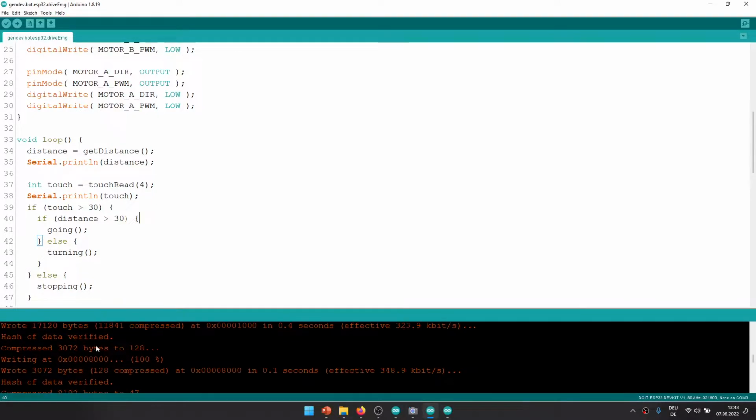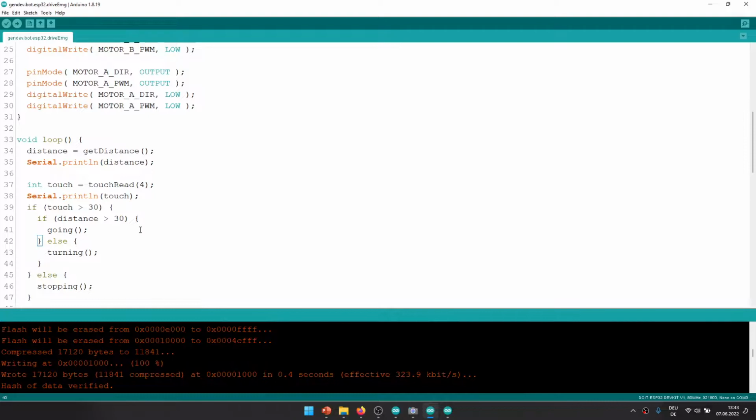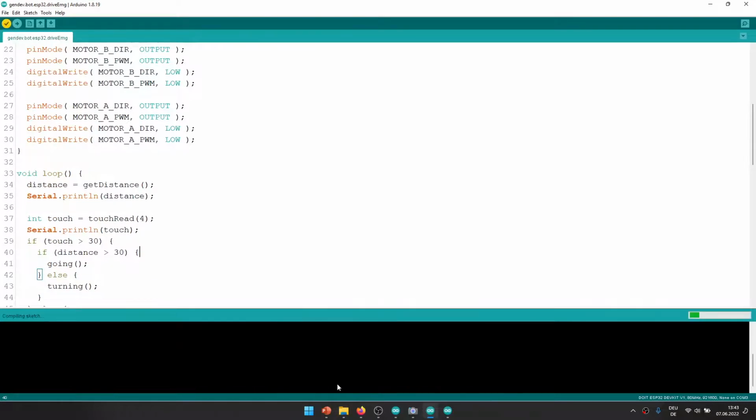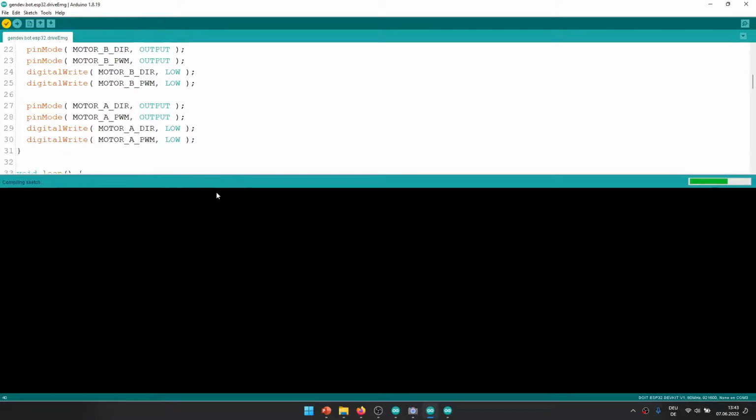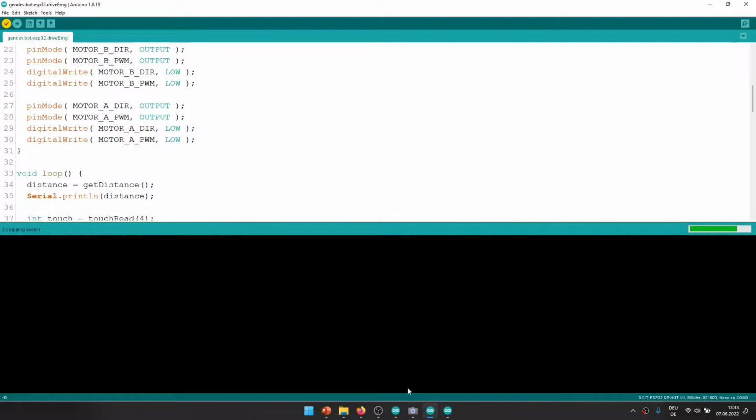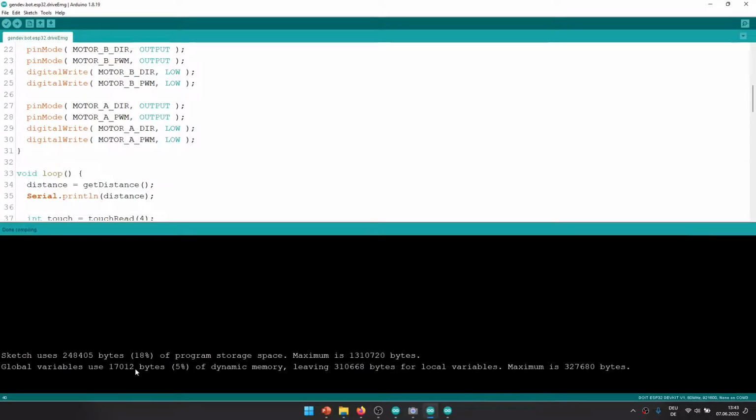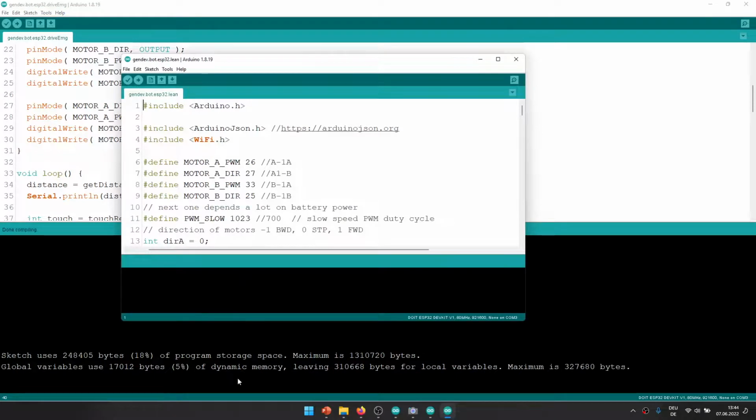the different versions that we have, let's just recompile this. So this was the one with the emergency off. I'm just going to recompile it so that we can see the output down here, because there are actually some differences between the versions and how much, say, memory consumption they have on the actual embedded chip. So here, this uses 18% of the program storage. So you might expect that if we have a less capable chip, or if we extend the program a bit, then 18% is good. But if we have something that uses more, then maybe that's not so good.